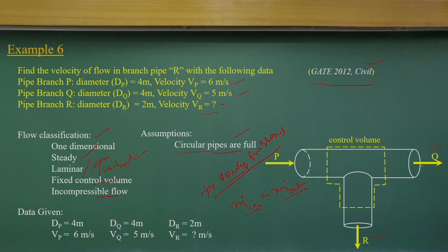So, in this case, because there are two outlets, the sum of these two mass outlets going out is equal to the mass influx coming in, the mass flux rate, the mass per unit time coming in. So, in a very simple way, rho Q in will be rho Q1 out plus Q2 out, that is the basic concept.